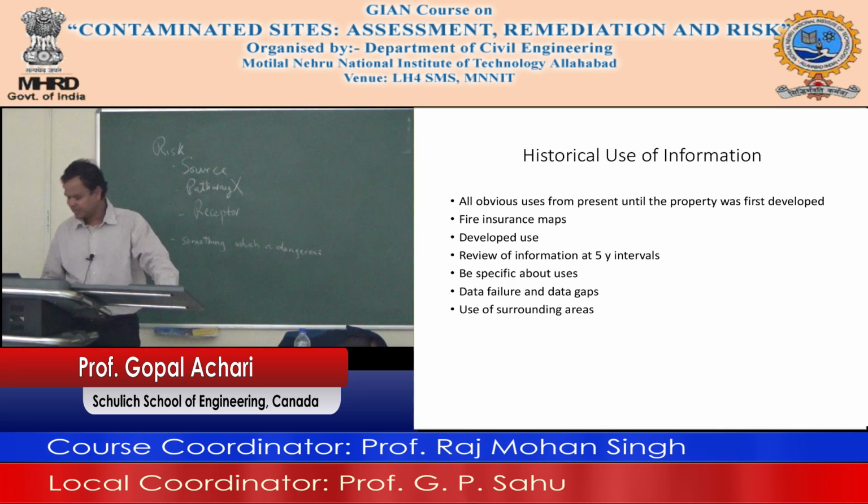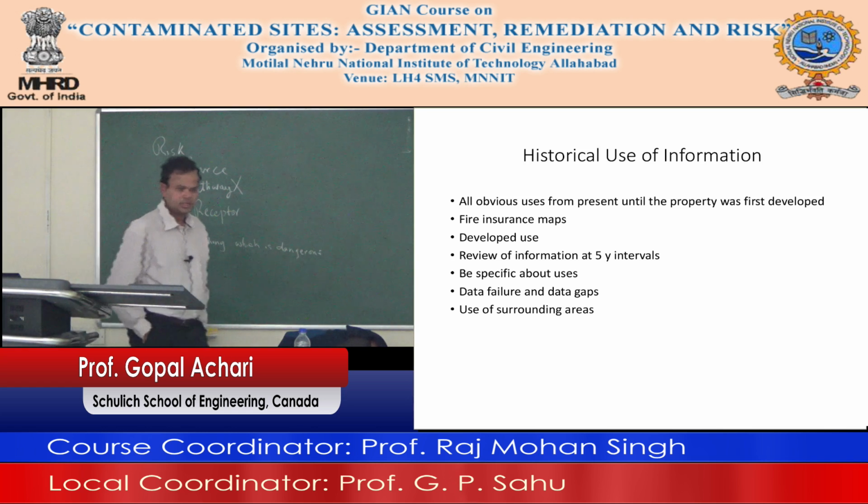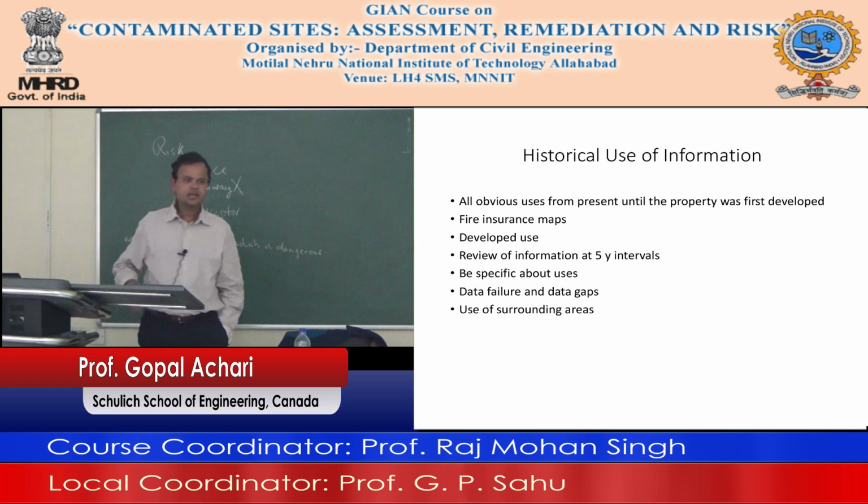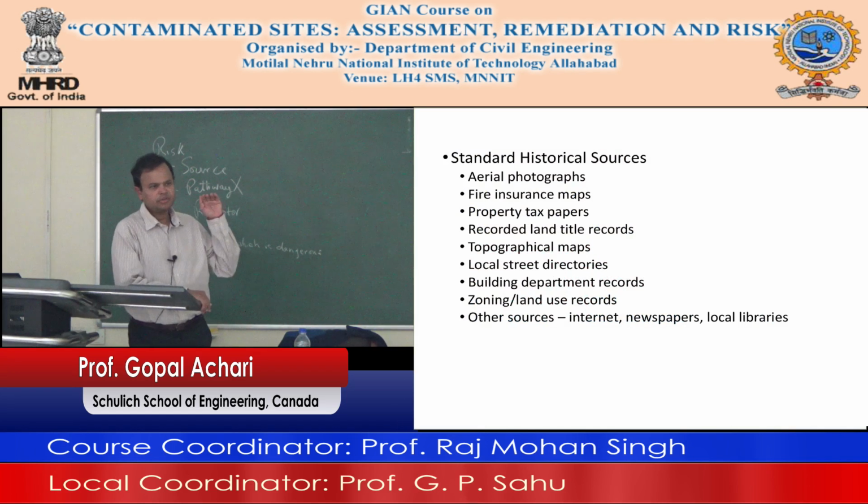Use of surrounding areas. What was the surrounding area used for? Okay, not only that particular area, but what did the neighbor use this site for? Okay. Look at aerial photographs. Now aerial photographs are taken every so many years. The government flies these planes to take photographs of what the area looks like. And these photographs are usually stored in the local libraries every 5 years or so.